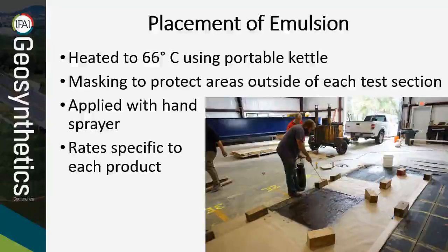Application of the interlayer products was done in a manner consistent with their installation in the field. Emulsions were determined for each product and applied using a hand sprayer. Masking paper was used to control the boundary around each test section.